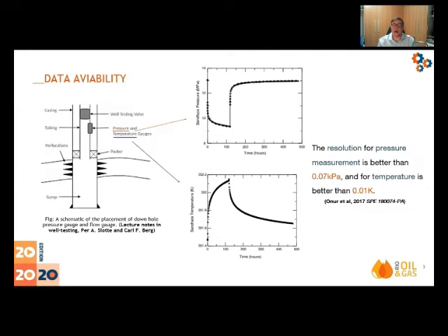The pressure data are commonly used, but due to advanced well sensing, temperature sensors have already been installed, and these sensors have resolution capable of capturing the small variations that occur during the well test. In the oil field, the temperature data is usually used to estimate the formation temperature, the production of gas, and the leaking along the well. However, recent studies show that the temperature transient can be used to better characterize the reservoir properties. Another important piece of information is that the temperature sensor resolution is better than the pressure sensors.